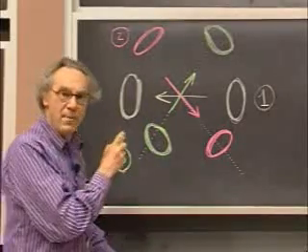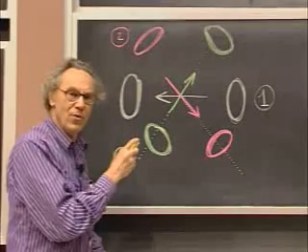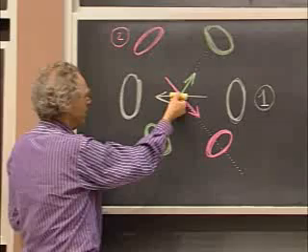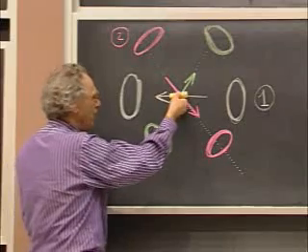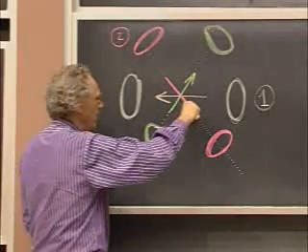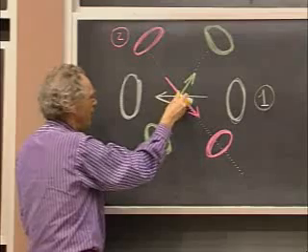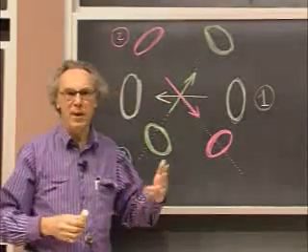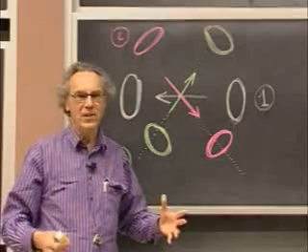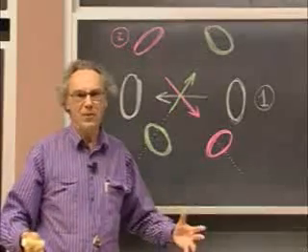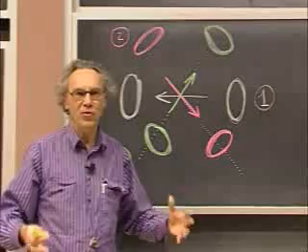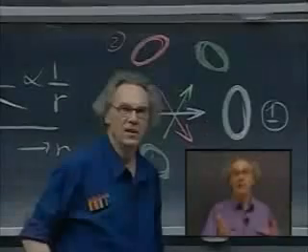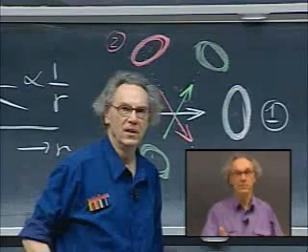And look now what has happened. In one complete period, the magnetic field started out like this. 1/3 of a period later, it was like this. And 1/3 of a period later, it was like this. So what we have created is now a rotating magnetic field. And it rotates in one period, all the way around, 360 degrees. Okay, let's now go back to my original lecture.